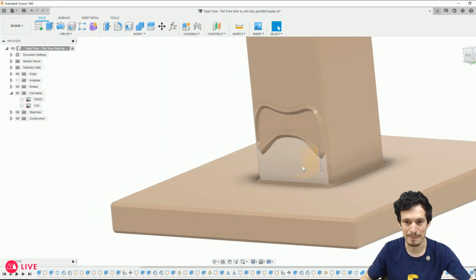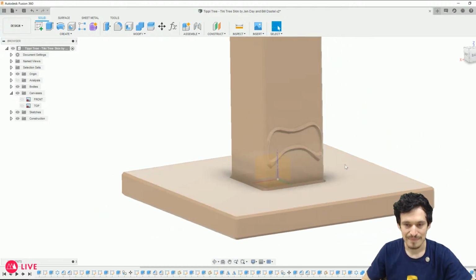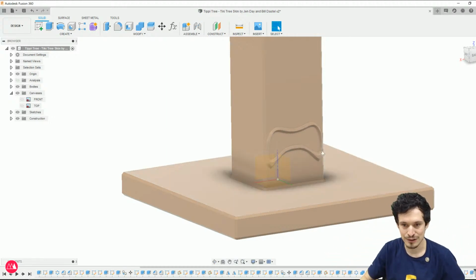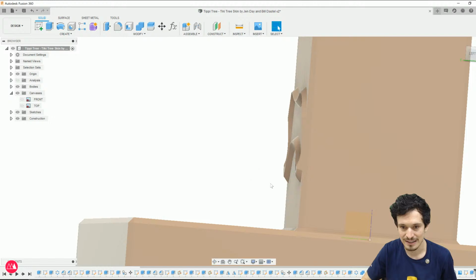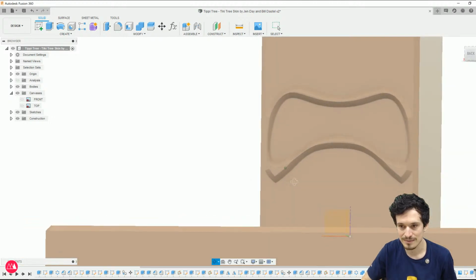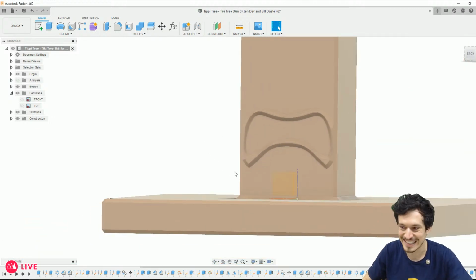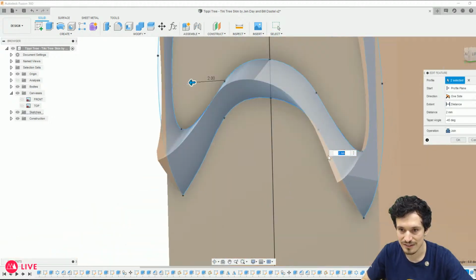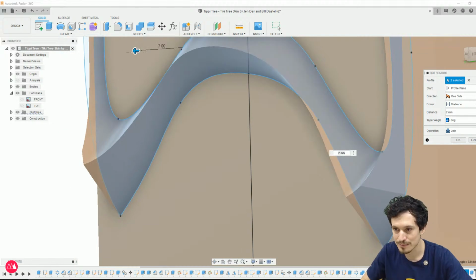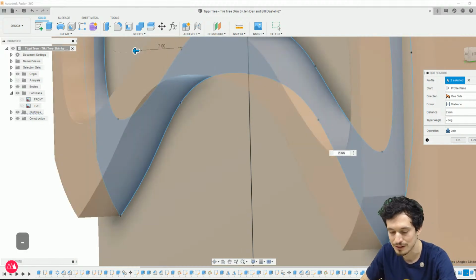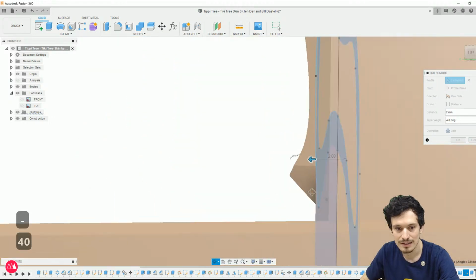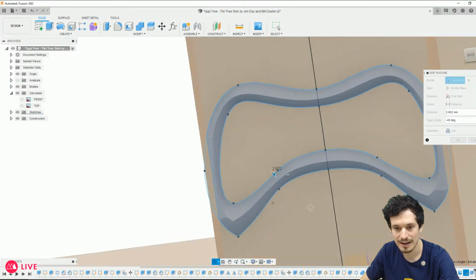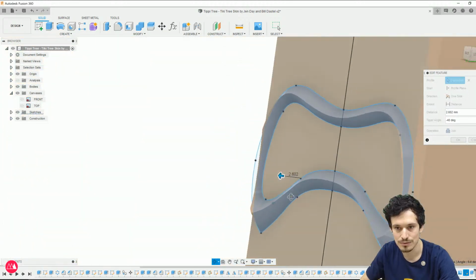Should I have the lips be a little beefier, or? This strategy is actually really fun, just to have the drawing and then do a tapered extrude. That's a good way of getting no extreme overhangs. It does look like a game controller, doesn't it? Like I said, I could do a slightly more aggressive taper. So let's see what happens if I do minus 40. As you can see, it starts popping out a bit more. Like that. That's pretty cool.